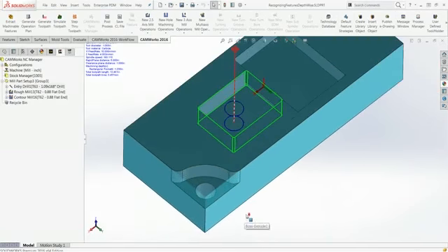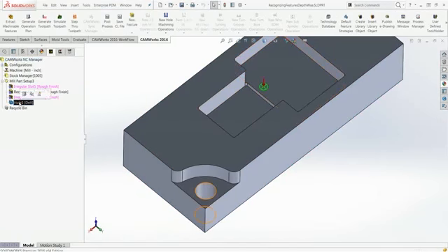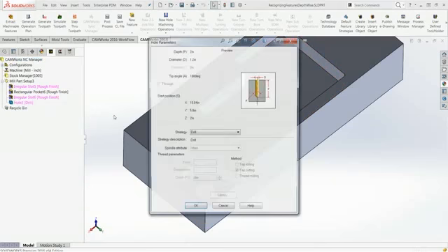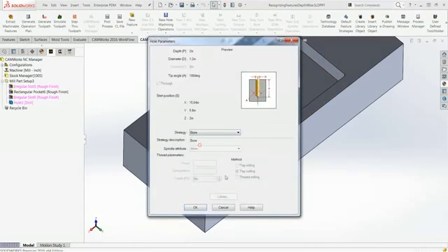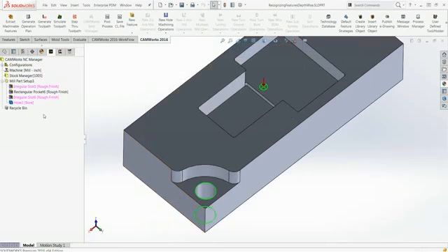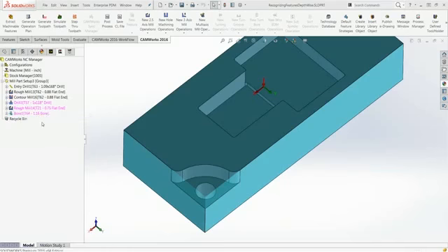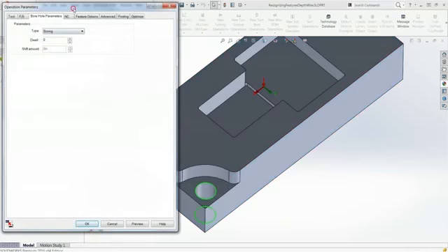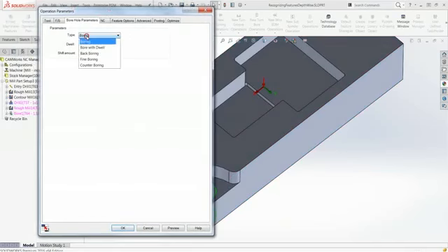If I come back into this part here and go into my drilling, I'm going to go into the hole settings and change the actual parameters to bore. And then I'll generate the operation plan. So what I'm showing you is inside of the bore settings. If the type is boring, we can actually add a dwell and a shift amount now on our boring toolpaths.